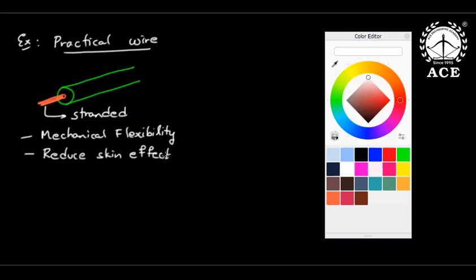I don't want to explain. Even though I know the reason, you will be taught skin effect in machines and power systems. So two things. First of all, copper is stranded to increase the mechanical flexibility and to reduce the skin effect.